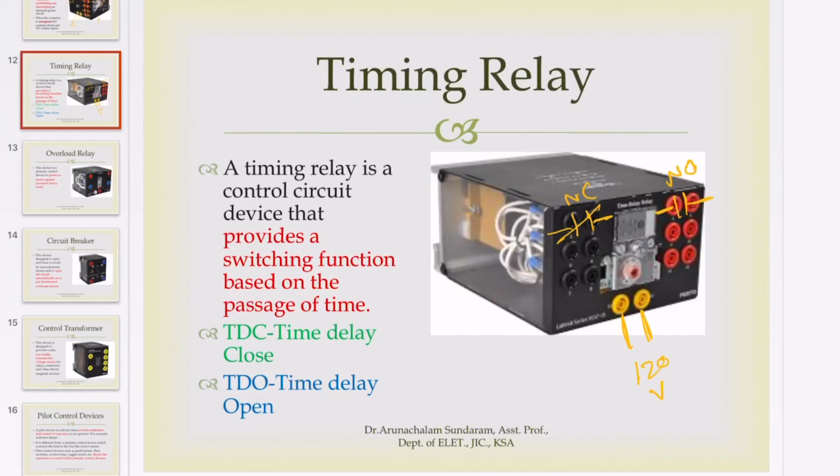It operates with time. So with time delay close, it is open, and after time, it will close. And with time delay open, after time, it will open. This is the extra feature that it has over the contactor.